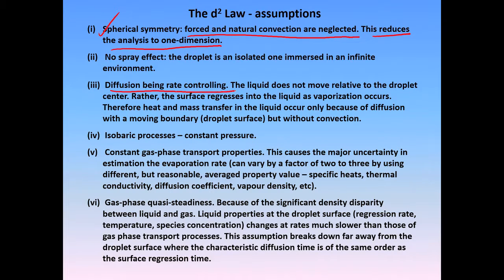Diffusion is the rate controlling parameter. That means the liquid does not move relative to the droplet center. That means there is no internal motion of the liquid, got it. The surface regresses into the liquid as evaporation happens.